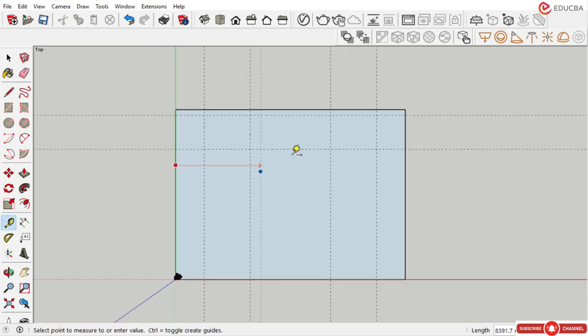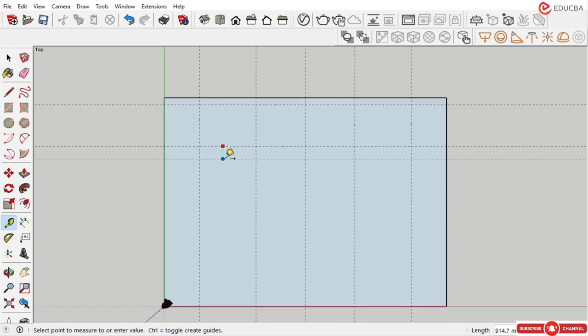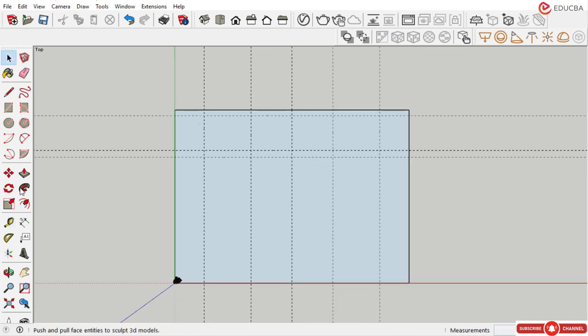Now make the center line from here to here. So this is the midpoint. I have designed the center line here, and just put another line for the curve. So here I will put around 600. So this is the 600 line, and my curve starts from here. So I will choose this 3-point arc. So from here to here. So this is the curve line I have just drawn here, and now copy this curve line wherever we want.